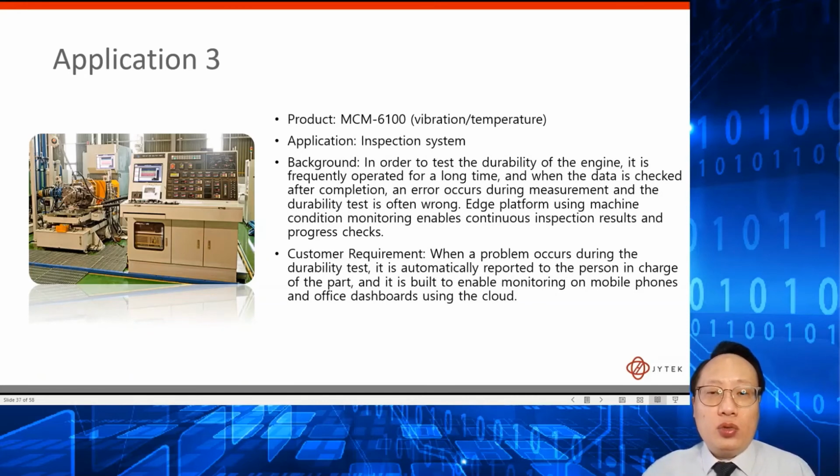The third application is also measuring both vibration and temperature, and this is actually for an engine test bed. Basically, this setup tests a car engine, used in R&D, quality assurance, and so forth. In this case, the test can run hours, days, or even weeks. So they need a system that will automatically collect the data, save it into the database, and also report any anomalies if something happens during the test. And their technicians are able to access the data through an IoT dashboard using tablets or mobile phones, even though they are not at the test site.